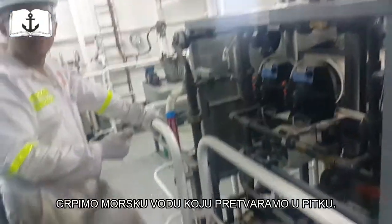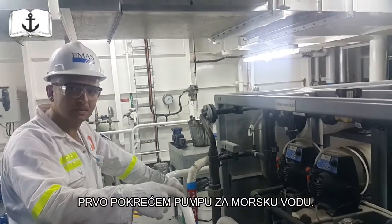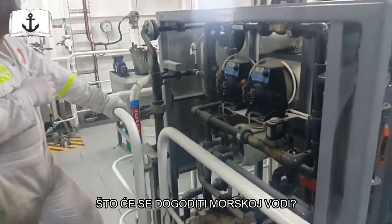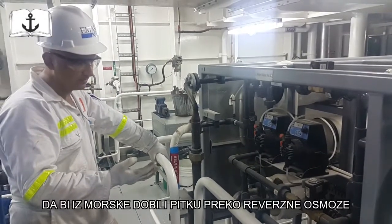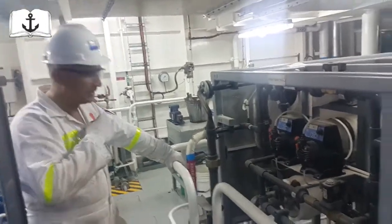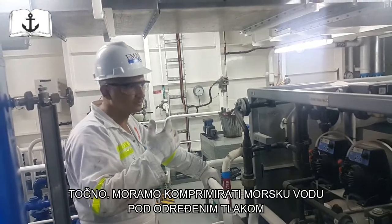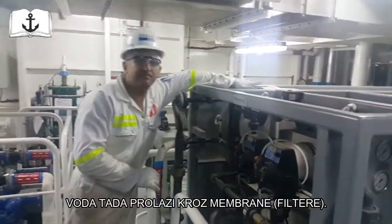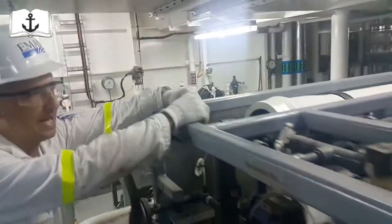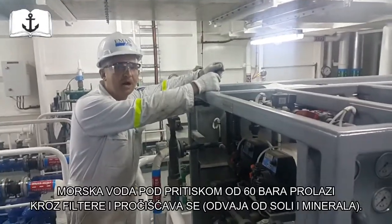We need the seawater to make fresh water. For these units, I need to start the seawater pump to get the seawater to the unit. So you supply seawater by the pump. To make fresh water, the process is called reverse osmosis. Basically you need to compress the salty seawater to a certain pressure and push it through the membranes. The membrane is like a core material inside, some kind of filter that separates the salt and the minerals from the water.